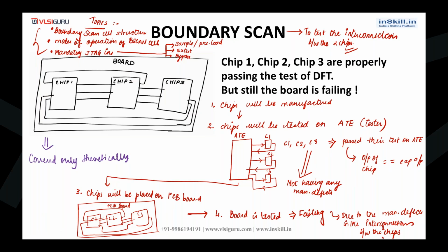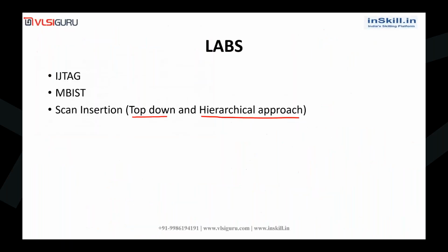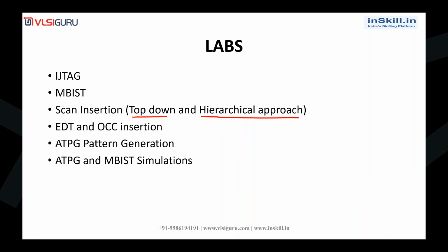Okay, for labs these are all the things that will be covered: JTAG, MBIST, scan insertion. For scan insertion there will be two approaches, top down approach and bottom up approach, and we will be covering both. And then EDT and OCC insertion, ATPG pattern generation, ATPG and MBIST simulation. So these are all the topics which will be covered in our labs.